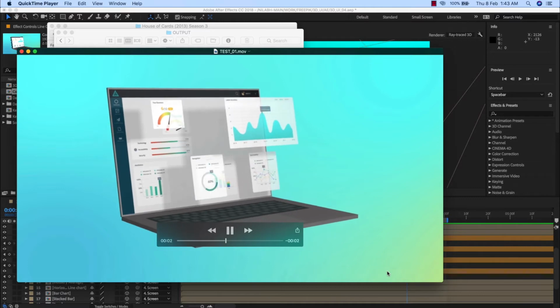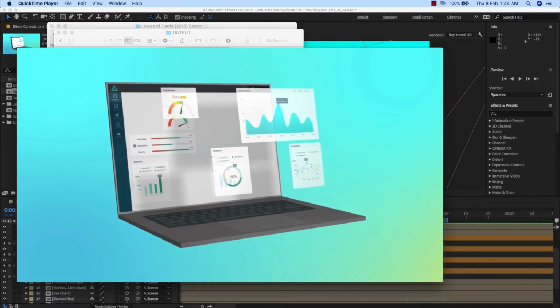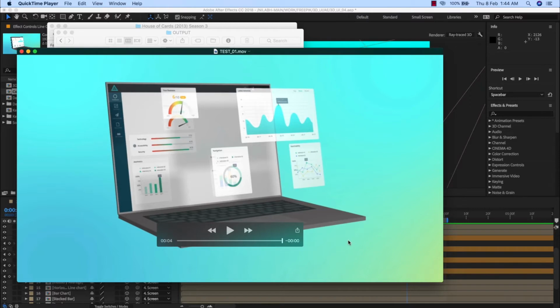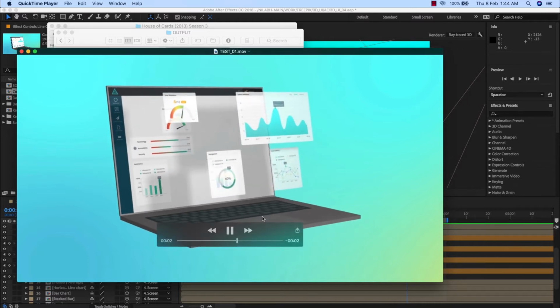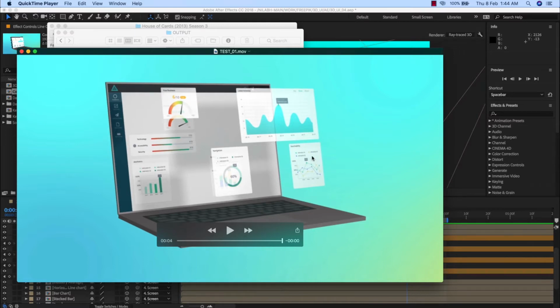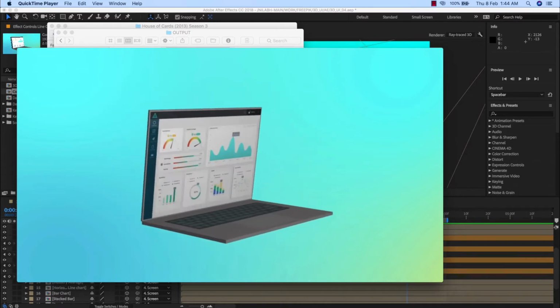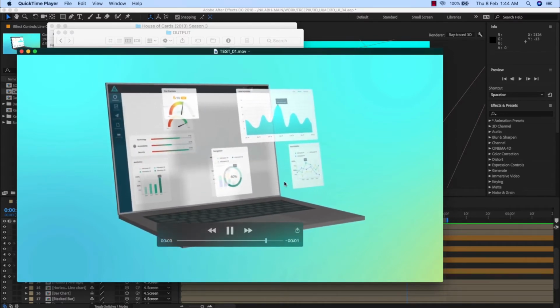So here is the output that we have rendered so far, and this is almost done. We can obviously go ahead and animate the camera also. It takes a little time in this renderer to actually render all of these frames, because as I mentioned, it is really heavy on your system, and if you do not require the refraction and opacity and all of these additional settings, then the first option makes sense. But of course, to take it a level ahead and have all of these details and more beautification, better lighting and better shadows, then of course this technique, the ray trace 3D, is much better.